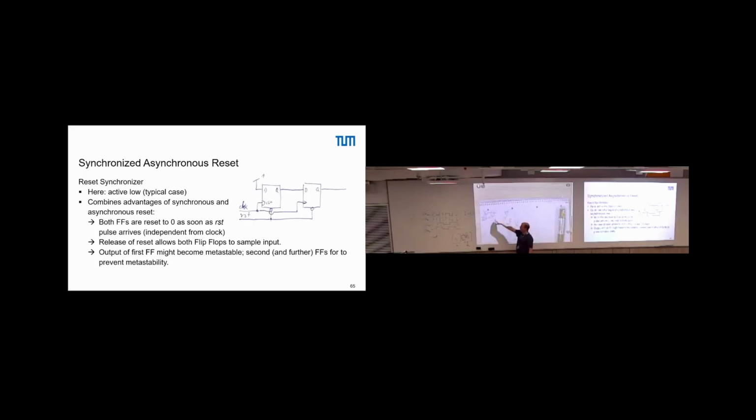Because set is synchronous, reset is asynchronous. We have no problem that we may start off from an invalid state because we can well compute the timing. And we have the benefit, we do not depend on the clock with the reset. As soon as we push a reset, it's there.